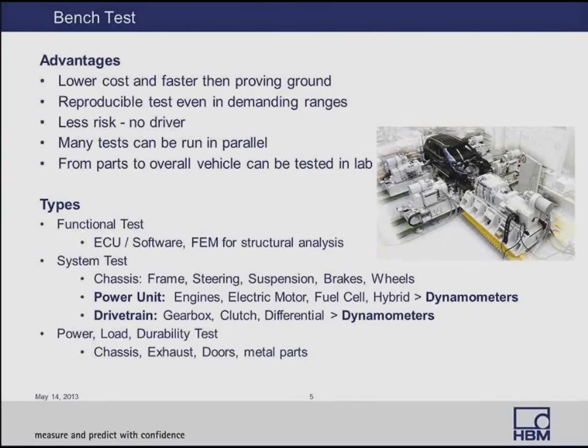These types of tests are further classified into three different types: functional tests, system tests, and durability tests, power load durability tests. In today's discussion, we are going to focus mostly on system tests. System tests can be further classified as chassis, power unit, and drivetrain tests. For today's discussion on dyno testing, we're going to focus on the powertrain test, drivetrain test, as well as the power unit test, both of which deploy a dynamometer entirely for this application.